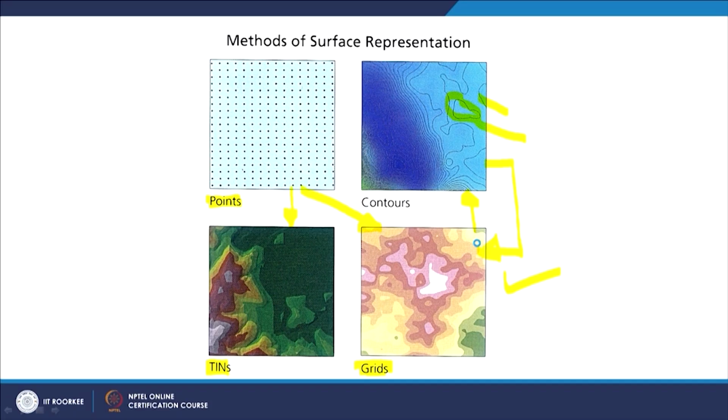And then using points, of course, you can create a surface. But suppose the software you are using is not capable of doing that, then there is a very simple method: you can convert this polyline first into points. Such tools are always available, and then using points you can create a surface. These software tools you have to use judiciously and very intelligently. Basic tools are there, only you have to find the best way to create a surface.